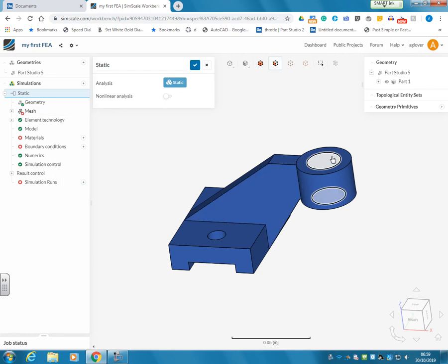First of all, as we've described in class, you need to create a mesh. The way it works out the stress here is to calculate it over thousands of little elements in here, hence finite element. There's a finite number of elements in here, and we're going to analyze it. Now the more elements we can add, the more fine detail we're going to get about the stress, but the more elements we add, the longer the computing time is going to take and cost.